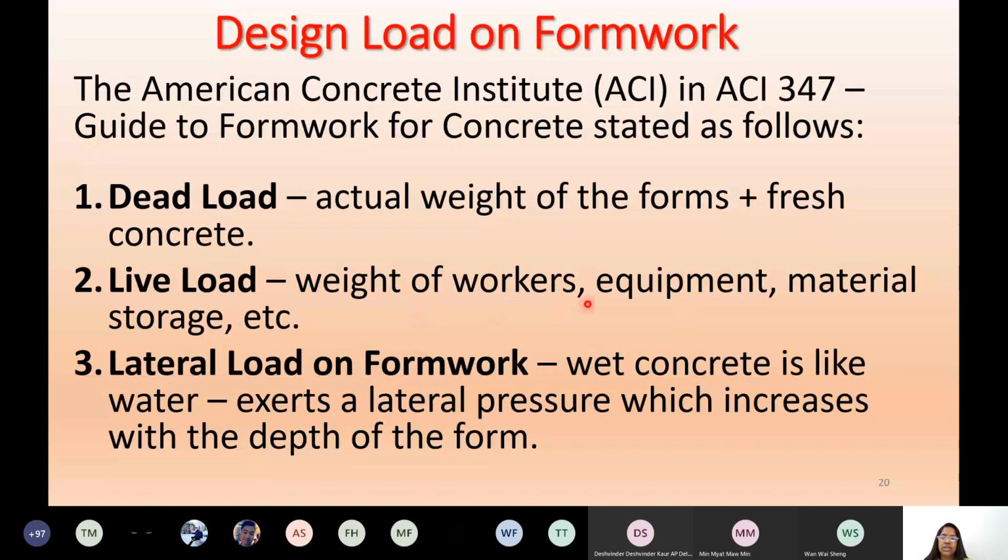Live load is the weight of the workers who are coming and pouring the concrete, carrying the concrete, machinery, equipment, and material storage. Sometimes the materials are stored on the top and they may be mixing concrete beside to pour into the formwork. So all these types of moving loads or changing loads. The material will be there, they're mixing concrete, and once mixed and poured, the place is clean, right? So changing loads are live loads.